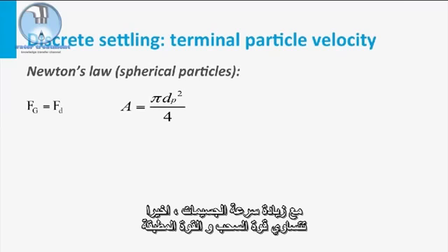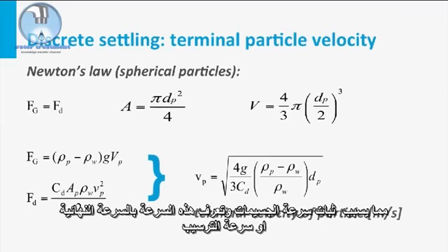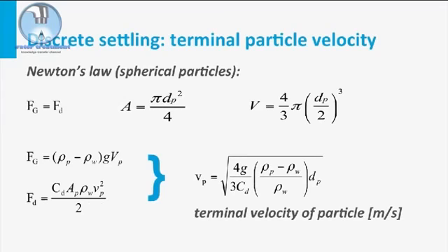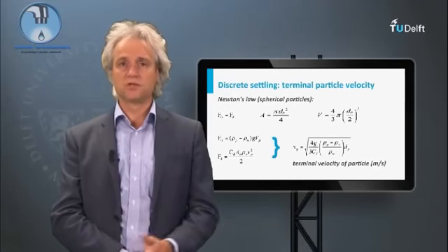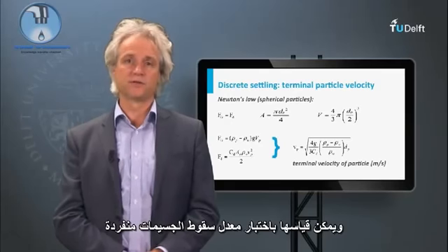As the particle increases in velocity, eventually the drag force and the applied force will approximately equate, causing no further change in the particle's velocity. This velocity is known as the terminal velocity, settling velocity or fall velocity of the particle. This is readily measurable by examining the rate of fall of individual particles.